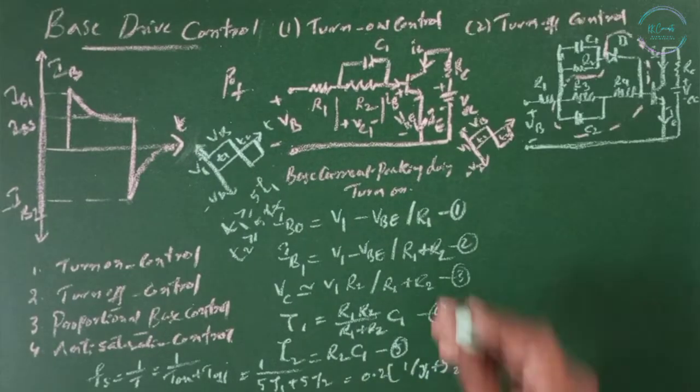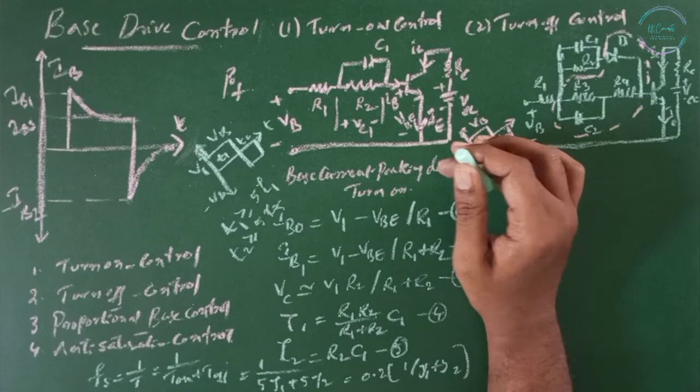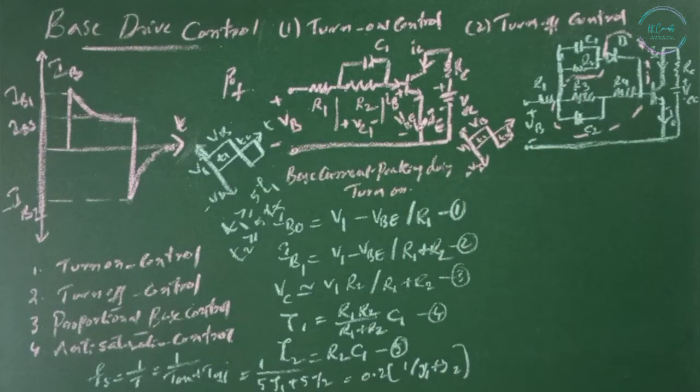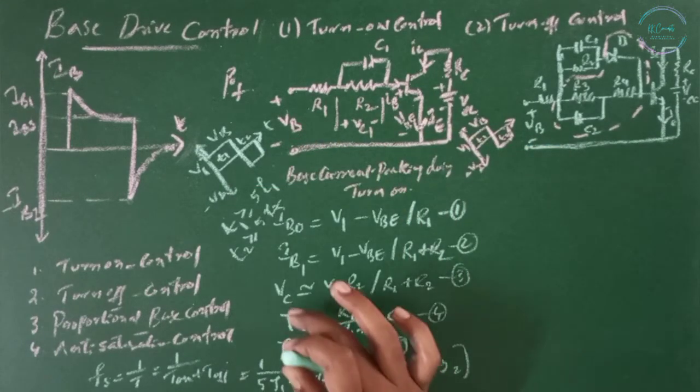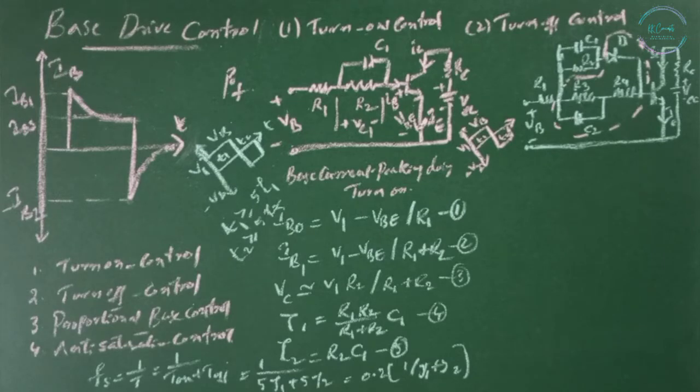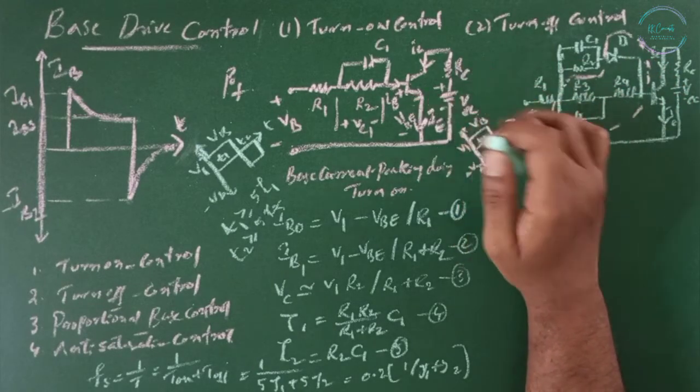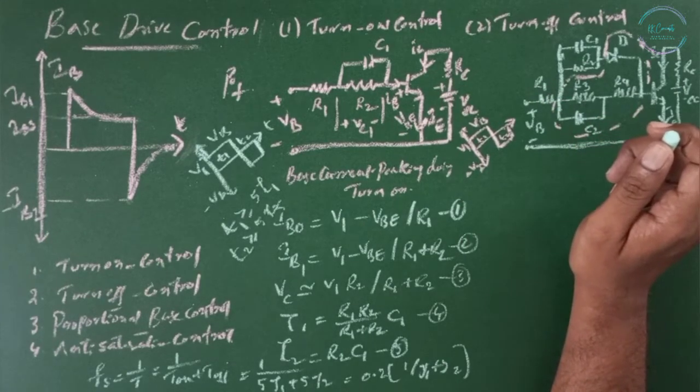If the input voltage turn on position is charged to minus V2 during the turn off, the capacitor voltage Vc here is added to V2 as a reverse voltage across the transistor. There will be base current peaking during turn off. As the capacitor C1 discharges, the reverse voltage will be reduced to the steady state voltage V2.